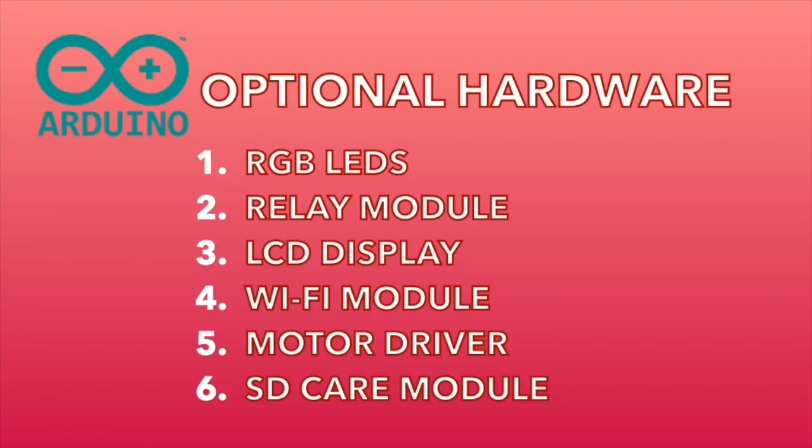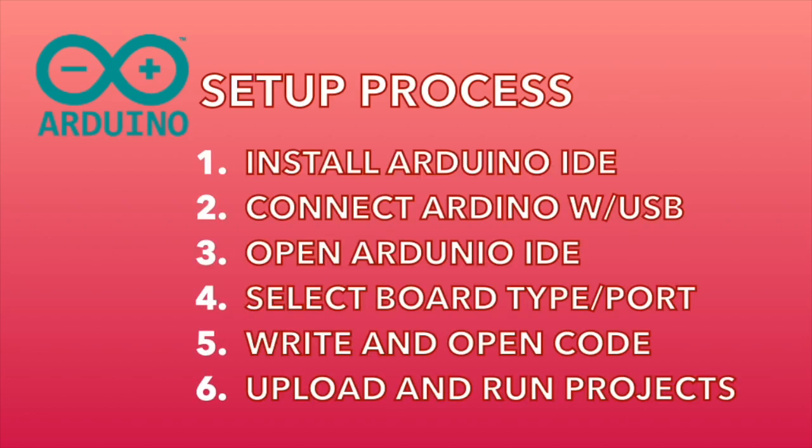Setup process. First, install the Arduino IDE, integrated development environment, on your computer. This software is used to write and upload code to the Arduino board. Next, connect the Arduino board to your computer using a USB cable. This provides both power and communication between the computer and the board.